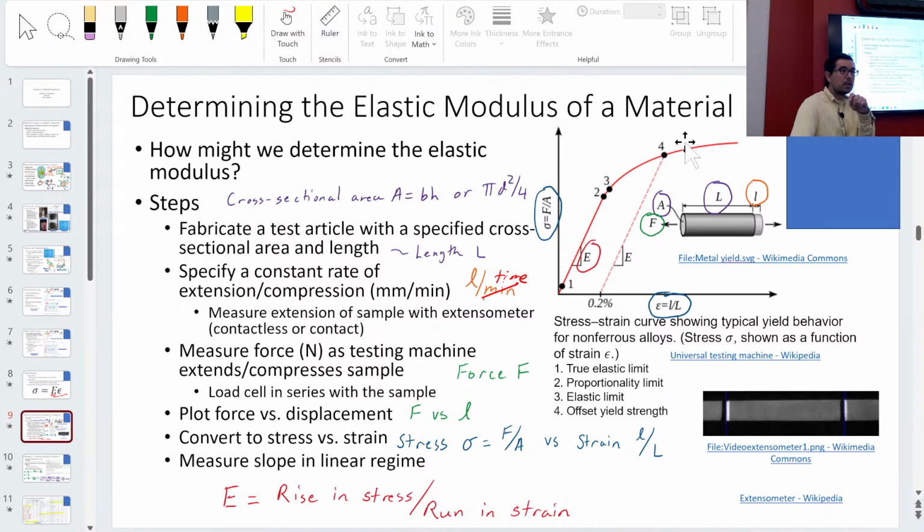Okay, yes. So it starts to the right on the strain axis. Does that mean, after the first time you stretched it, it is now permanently longer, if you're not touching it? Yes. So as long as you stay between points 1 and 2, or even point 3, and you go back down, you go back right to where you started. It's a nice linearly elastic spring essentially. We've talked about bars as springs, so you go back.